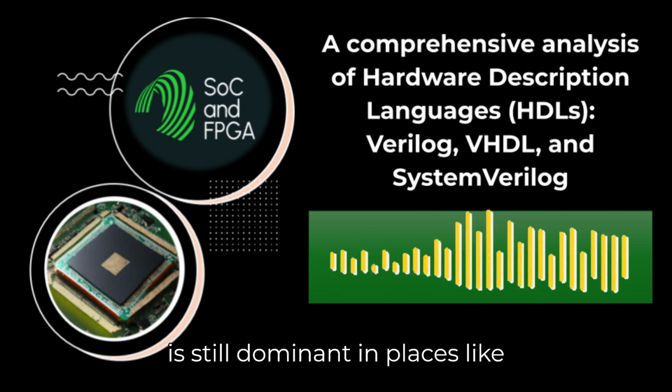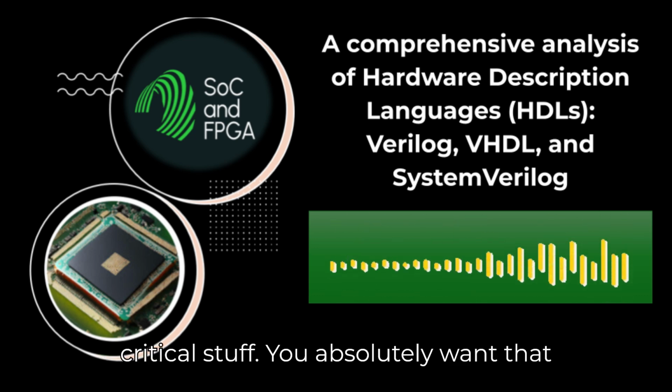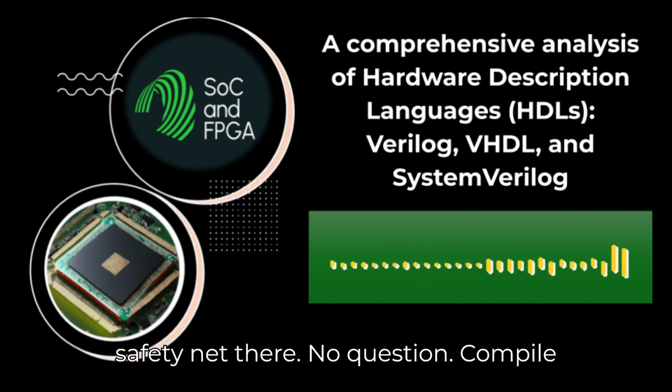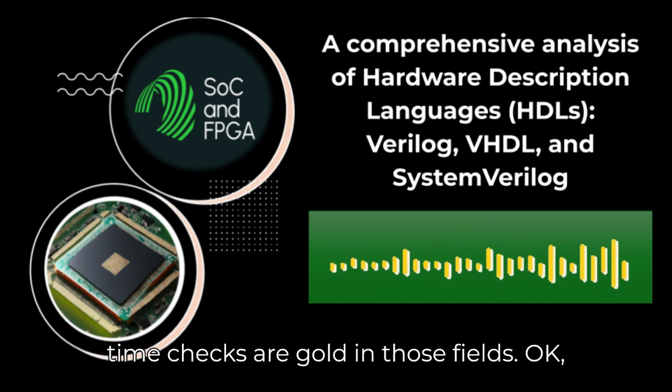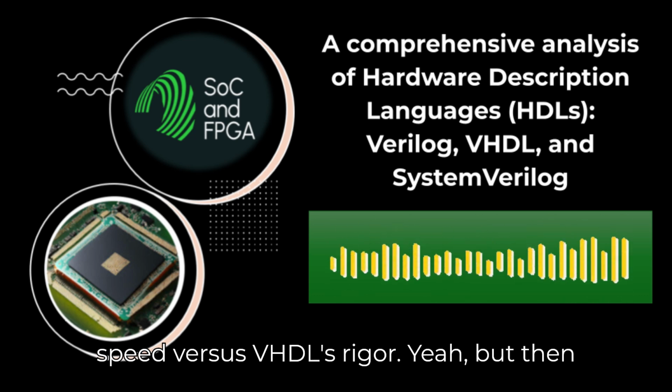That's why VHDL is still dominant in places like aerospace, defense, mission critical stuff. You absolutely want that safety net there. No question. Compile time checks are gold in those fields. Okay, so for years you had this dynamic. Verilog's speed versus VHDL's rigor.